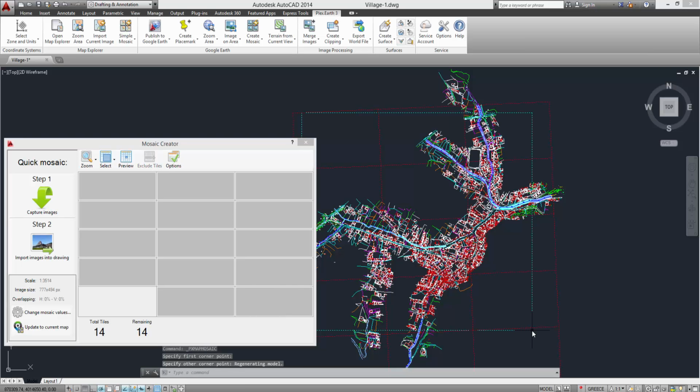Mosaics are the result of several smaller images blended together, the scale and resolution of which you have already selected in the Map Explorer. The preview feature which appears on your project background shows the exact placement of the tiles along with their boundaries, shown with a red color, as well as the outline of your mosaic area selection, shown in blue. If the resulting number of tiles required to create the mosaic do not cover your needs, for example too many for a simple draft project or too few for the quality you require, you can edit your selection.